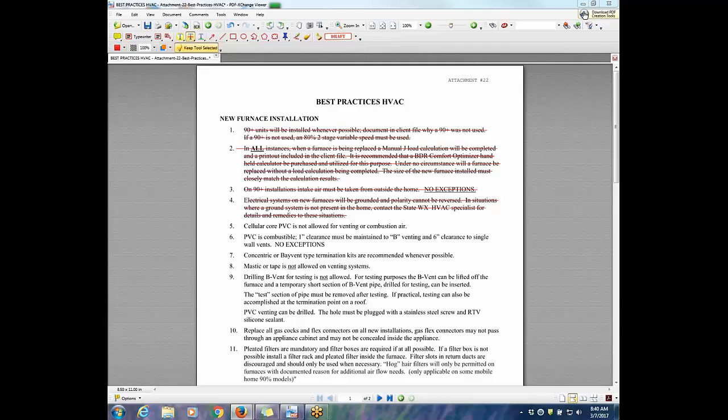And here's the other problem. If I call Johnstone's and say, send me 20 feet of 3-inch PVC pipe, guess what they'll send me by default? Cellular core. I have to specifically ask for Schedule 40 solid core PVC pressure pipe. Is it just the Schedule 40? Like, what is it that we're looking for when we do this?